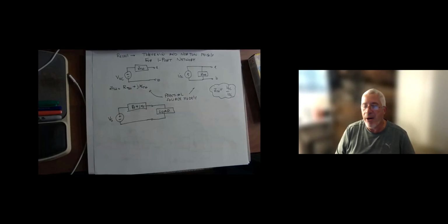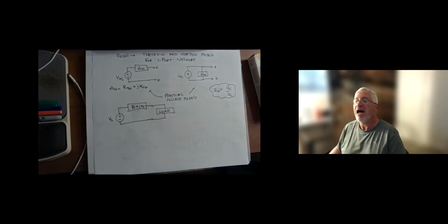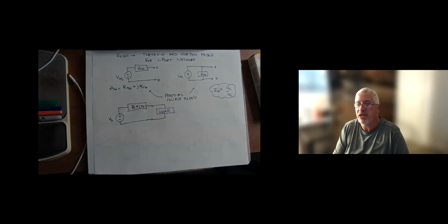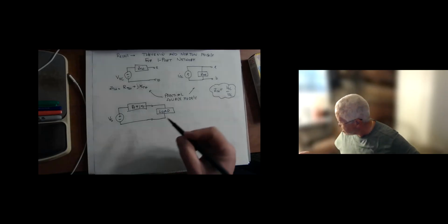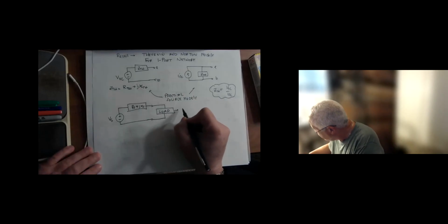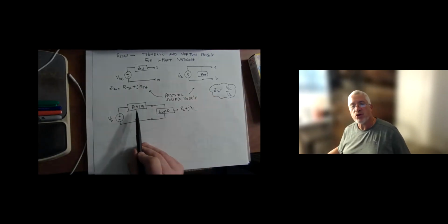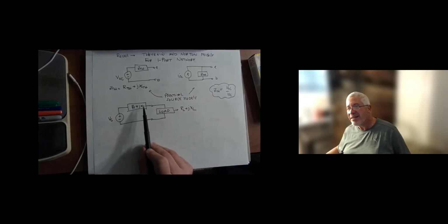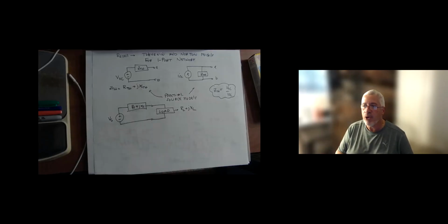Then we can talk about how we send maximum power to that load. I've avoided doing the maximum power discussion for sinusoidal circuits because it's so late into the semester. I feel like I'm packing content, but this is context. If that load is some RL plus jXL, we can actually design the load in relation to the source resistance and the source reactance, the source impedance, if you will, so that the load gets maximum power. So there is a discussion that we could have.